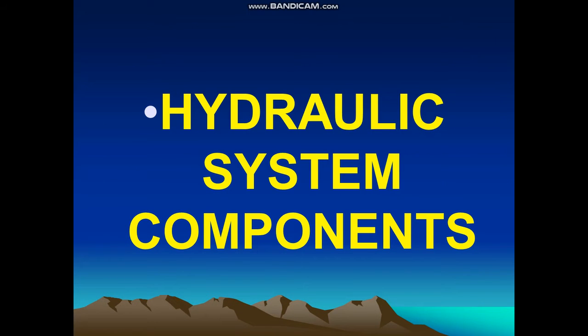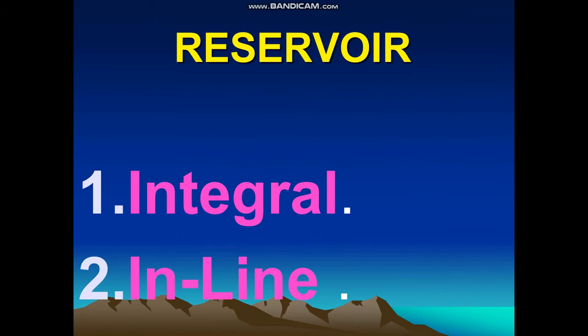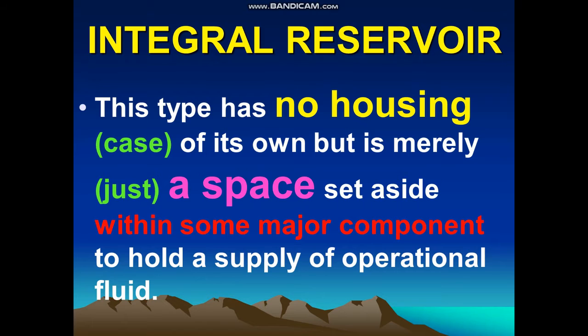Today we will talk about the hydraulic system components and we will start with the reservoir. We have integral reservoir or inline reservoir. The integral reservoir has no housing or case of its own but is merely a space set aside within some major component to hold a supply of operational fluid.